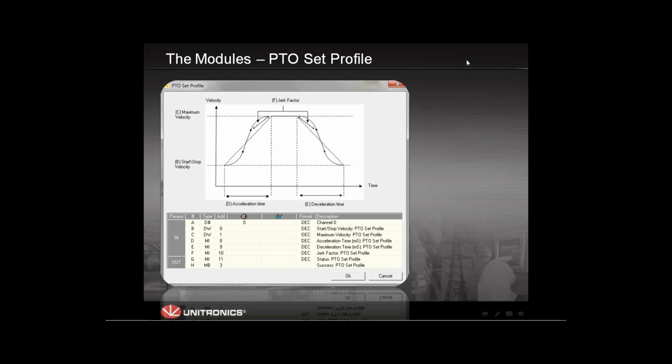The minimum velocity is the velocity at which the motor starts running, because a stepper motor doesn't start to run until a certain input of speed, of velocity. So these are values that you can get from the datasheet of the motor itself. This is not related to Visilogic. It is related to the motor that you're using, that you're controlling.